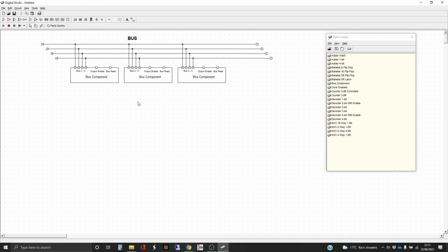When a data transfer is happening from one component to another, and registers and CPUs have a lot to do in terms of data transfer and moving numbers around, then one of these components will be connected so that its bus connections here are outputs. You call it writing to the bus, but it actually determines the status of the bus: which lines are high voltage, which means a 1, and which lines are low voltage, which means a 0 in your binary numbers. And when a component is doing that, so the data is being held in the bus, any other components can read that data.